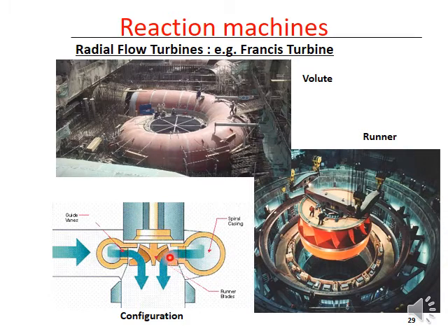So this is the runner. This is radial flow. You can see inside the runner the flow is radial and water flows out from the center. In the case of a pump, you have flow the other way: it enters here and leaves through the spiral casing. Here it is opposite, it comes in and goes down.